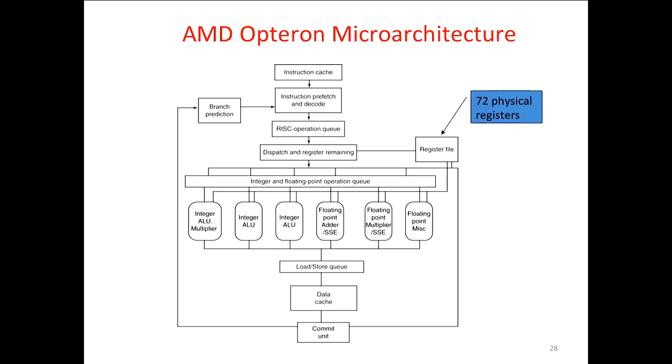Now, the interesting thing is that the x86 has a very complex instruction set. The MIPS you learned was very simple. The x86 was designed a long time ago in a different era and has many, many complicated instructions. Instructions that, for example, will copy a whole string in one instruction. They'll do a struct copy in a single instruction in the x86. And so the way the designers approached this is to take those complicated instructions and break them down into those little RISC things. On the fly, the hardware is taking the x86 instructions and converting them to little RISC-like instructions. And those RISC instructions will actually get executed inside the core of this processor, right?